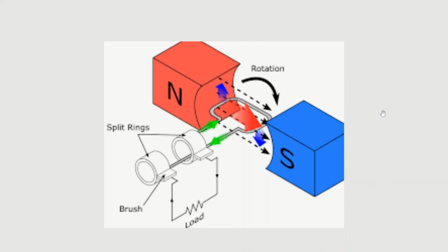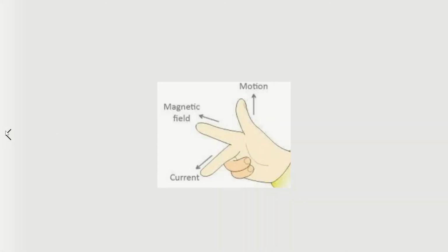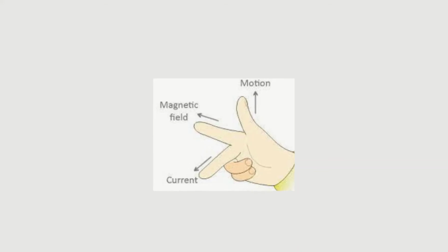As a side note, because the wire rotates, the wire ends are connected to a slip ring, so the wire is free to rotate. So here, this side of the wire is moving down, this side of the wire is moving up. So if you look at the right-hand rule, you'll see as that flips, the electrical current flips.